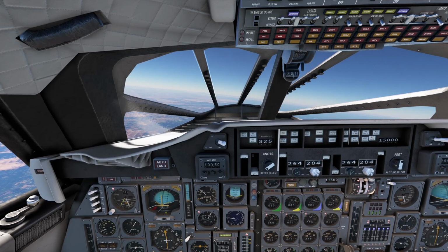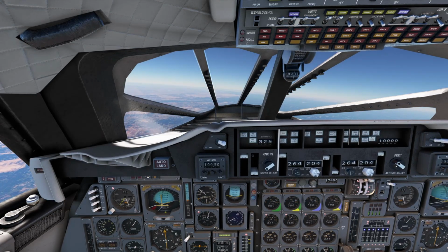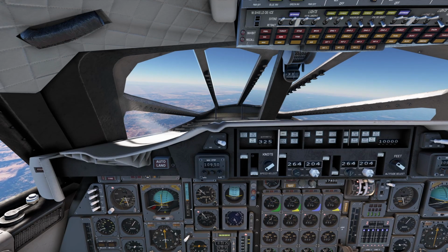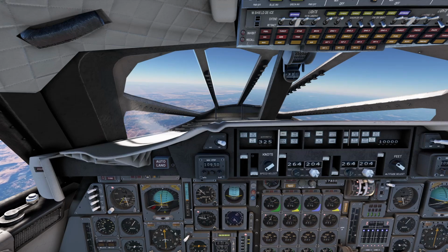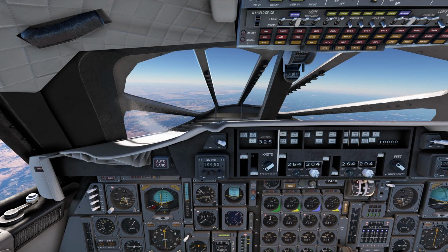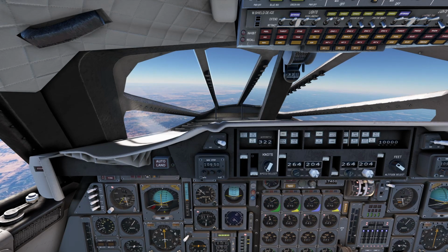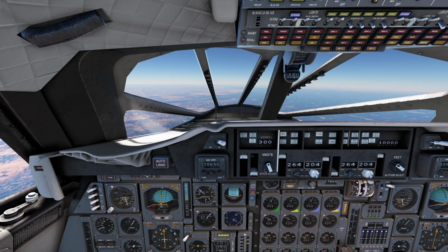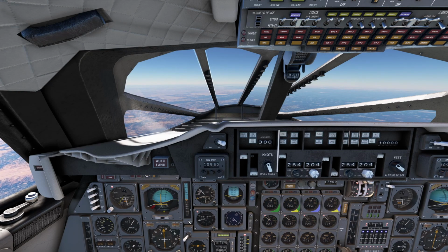24,000 down to 10. Again, altimeter doesn't play a role, and the landing lights we turned already on. I'm starting to gradually reduce speed. We are about 50 miles from the next waypoint, which is the entry point, or very close to the entry point to the ILS where we need to be at 2,000 feet.